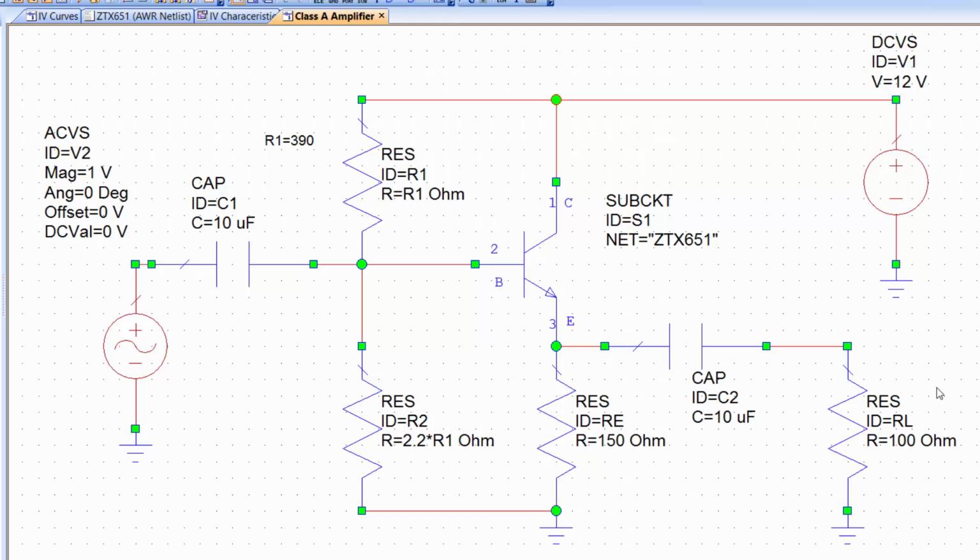Now, it's very important to stress the reason why we have the capacitors in here. If we didn't have capacitors, which act as open circuits at DC, when we connect our voltage source, some of the current that should be going solely through our potential divider and into the base may flow out and go into our source, and hence this would alter our bias. When our source is producing a signal, this would also alter our bias all the time as the signal goes through the various cycles. So it's very important to have these capacitors here to preserve the bias conditions that we've created. Those bias conditions are DC. DC does not go through capacitors, and hence this is a sufficient protection.